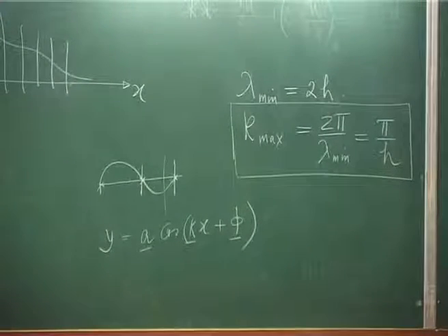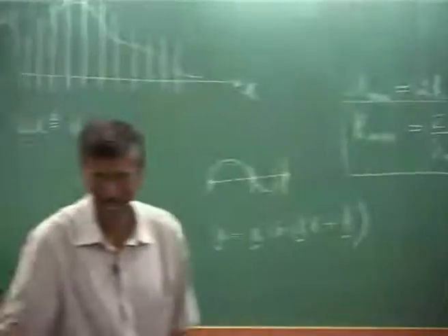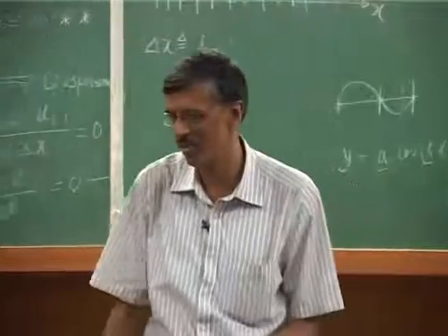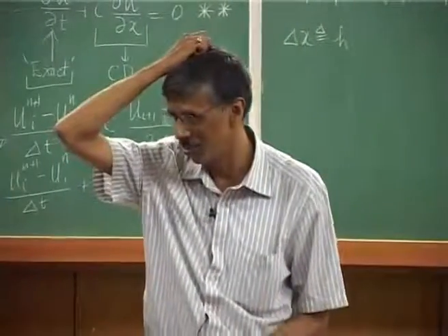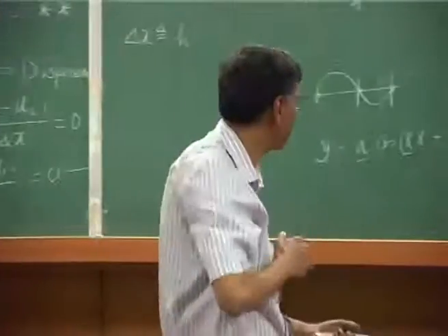I think most of you are familiar with it. You must have heard of it in your electrical engineering course, right. If you sample data at an interval of delta t, you immediately say what is the maximum frequency you can resolve, and that frequency you call the Nyquist frequency. So, it is the same thing. So, you understand the logic is exactly the same.